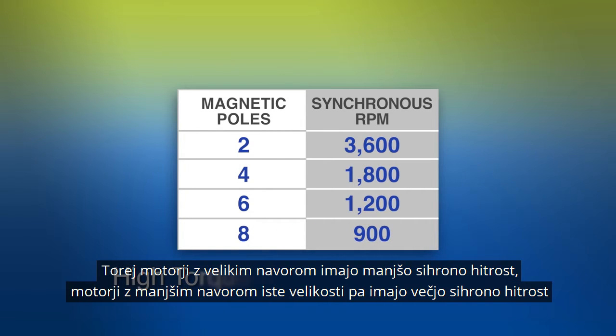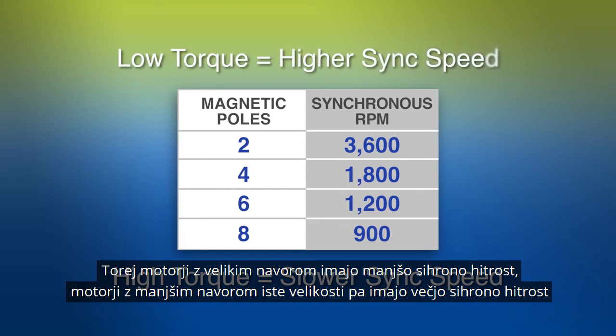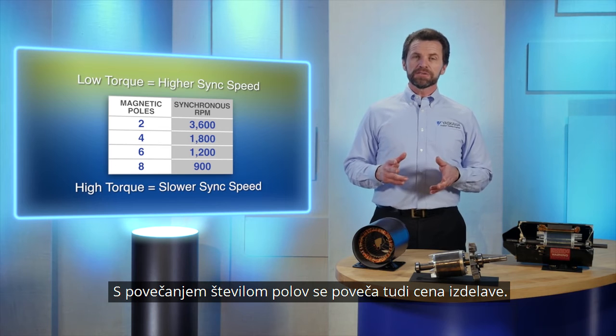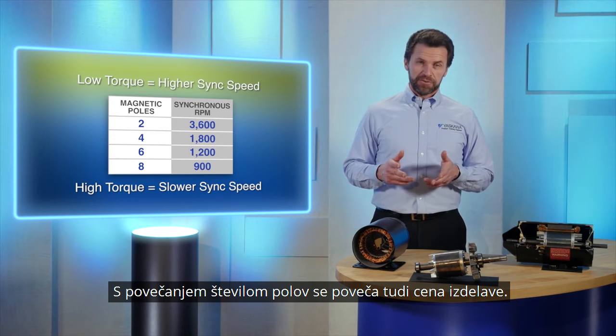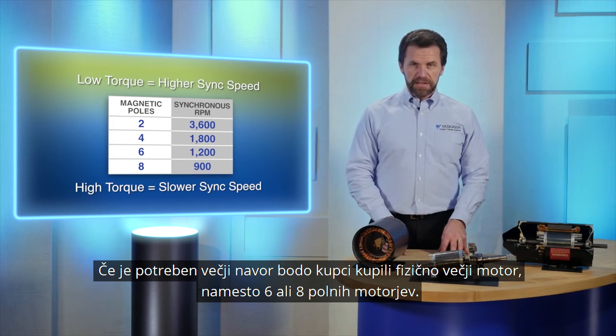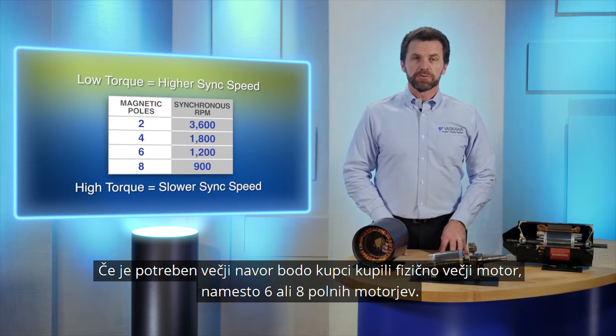So, high torque induction motors have slower sync speeds, and lower torque motors of the same size have less torque and higher synchronous speeds. One thing to note, as pole count increases, so does the cost of manufacturing. So most induction motors are 2- or 4-pole configurations. If more torque is needed, most people will opt for a physically larger motor instead of using a 6- or 8-pole machine.